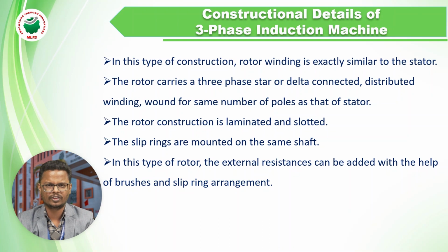So here we have some points. The stator construction of the slip ring induction motor is exactly similar to the stator of the 3-phase induction motor. Second, we can use star or delta connections according to our convenience. The rotor construction is also laminated to reduce eddy current losses. And here we use slip rings mounted on the shaft, so from the slip rings we can connect external resistance.